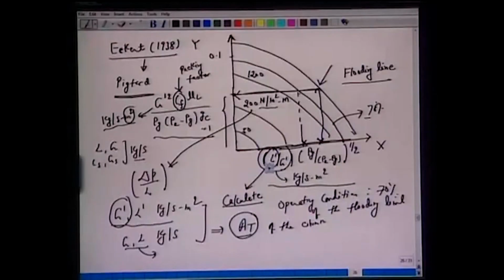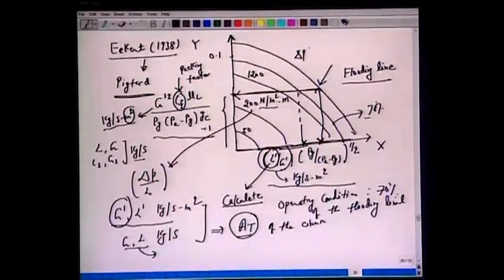So the two, they go parallelly, they're not in series. One has to do this kind of iteration. We will take an example where we have the mass transfer requirement, and then we have a different hydrodynamics requirement. Hydrodynamics comes from loading and flooding, and one of these curves will also give us the pressure drop, del P per unit length. Look at this unit, Newton per meter square per meter, which means the length should also come from somewhere else. So that's mass transfer.